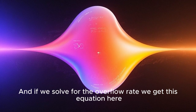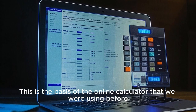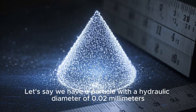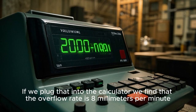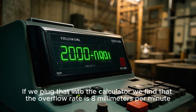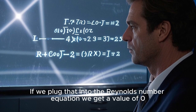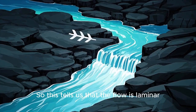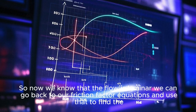Now, the Reynolds number is also related to the overflow rate by this equation. And if we solve for the overflow rate, we get this equation here. This is the basis of the online calculator that we were using before. Let's say we have a particle with a hydraulic diameter of 0.02 millimeters. If we plug that into the calculator, we find that the overflow rate is 8 millimeters per minute. If we plug that into the Reynolds number equation, we get a value of 0.015, which is less than 0.2. So this tells us that the flow is laminar.